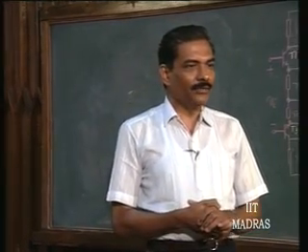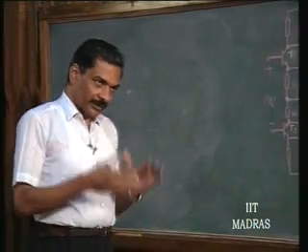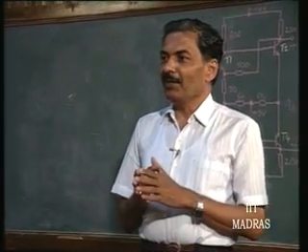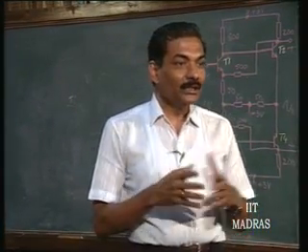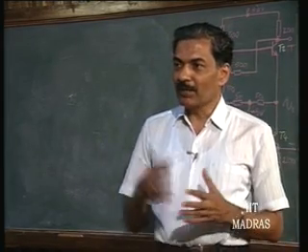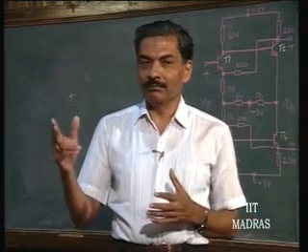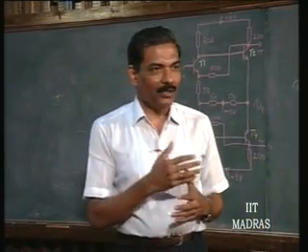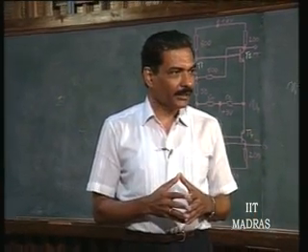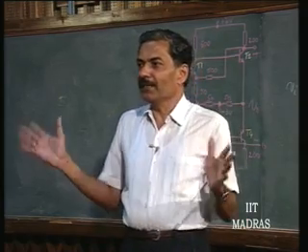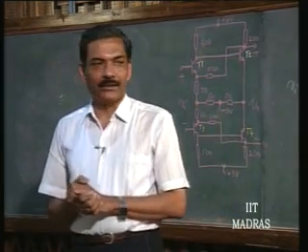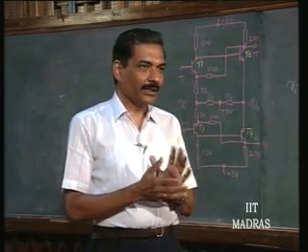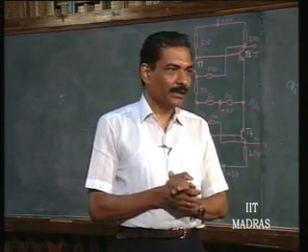Okay, and therefore, again the problem will be the problem of frequency compensation is more severe in this case, because how many time constants are there? Minimum. Okay. There will be 4 time constants to deal with, which may be of the same order of magnitude, okay, and therefore, it will definitely go into oscillations. And we might have to therefore take care of frequency compensation of the same type, right, that we had discussed